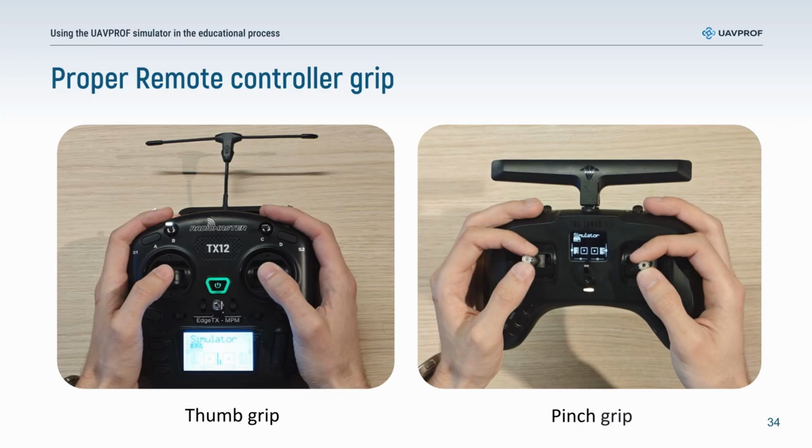The second option: the thumb lies on top of the stick and the index finger supports it from the side in front, creating a more stable structure. Both of these holding methods make it possible to achieve high accuracy with the slightest stick deviations and therefore achieve precise control of the drone's flight in manual mode.